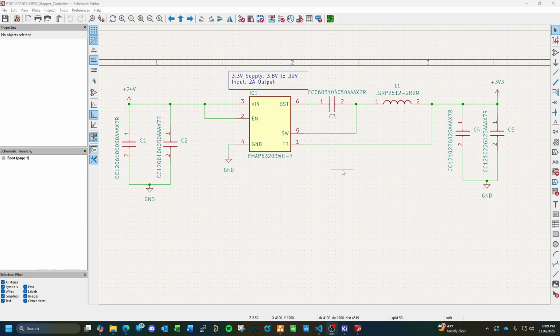So where we left off is we did the 3.3 volt supply. This is going to be the main supply for the ESP32. It'll handle pretty much just that. All your main logic, such as switches, like limit switches and control switches, is all going to be through the ESP32, but it's going to be 24 volt logic. 12 or 24 volt, but we're going to focus on 24. So we're going to be using opto isolators and everything for your inputs and outputs off of the ESP32. So for now, the 3.3 is just to power the ESP32.